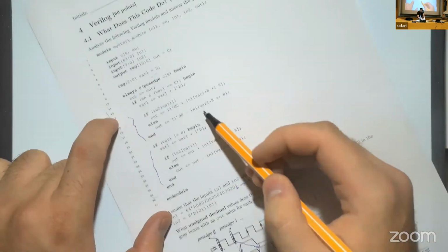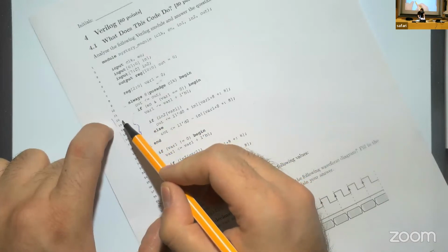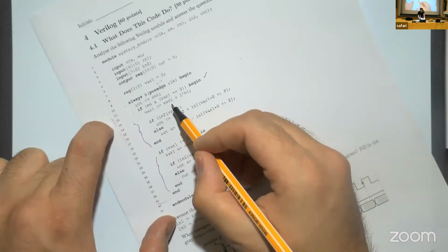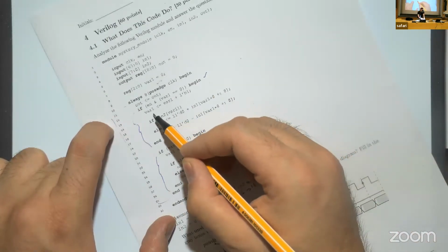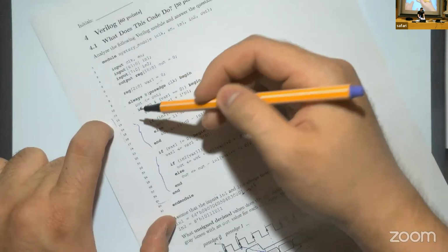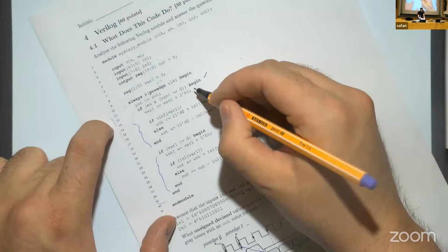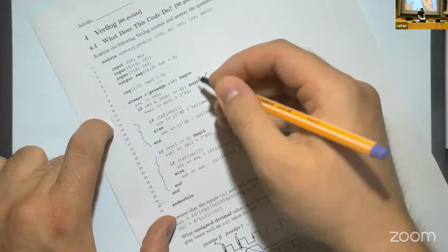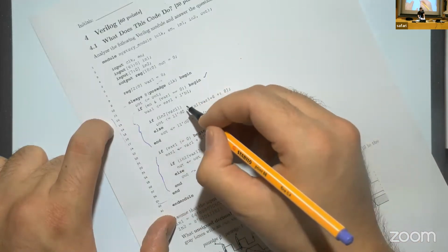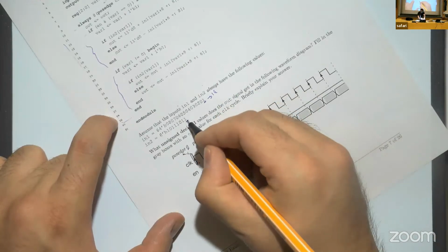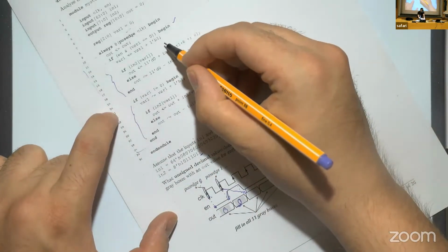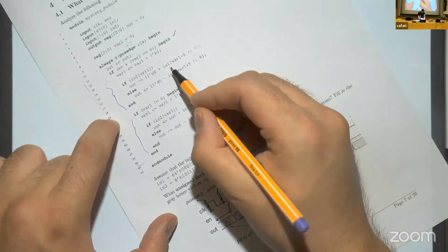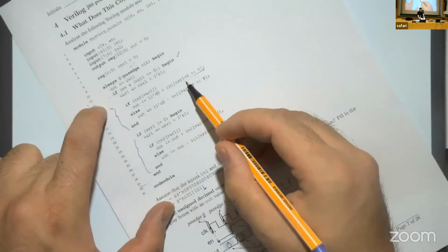That means this if clause, which is in the 12th line, will be satisfied. But variable 1 becomes 1 only after the always block is executed, so now it's still 0. We go into this if block, into variable 1's 0th bit. We check this 0th bit, it is 1. We also satisfy this one, and then out will become 0 plus this. I know you're not familiar with this one.